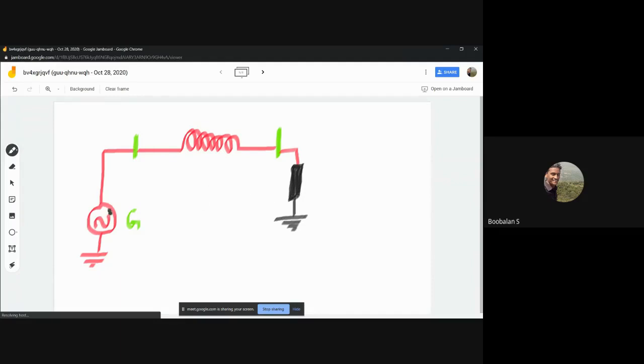A small power system, single generator. So totally bus number 1, and bus number 2, right? And we'll have a transmission line, which has its own resistance and its own inductance, right? Just assume that the line impedance is j0.1 per unit.